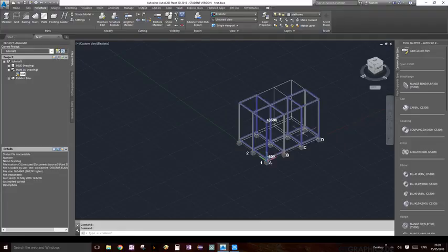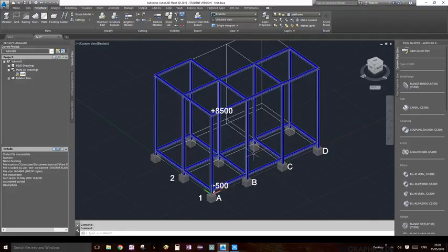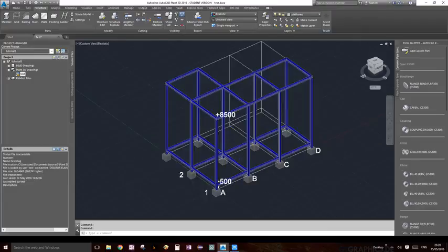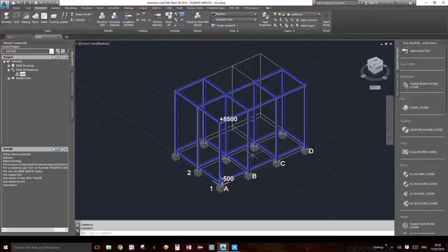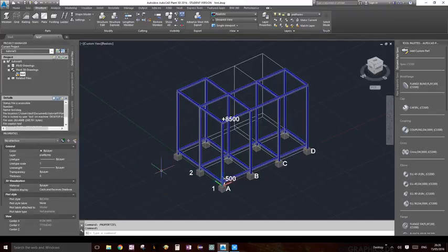Okay, so another thing that we're gonna use on and off quite a bit is the properties window. I find that it's sometimes super easy to just change the numbers than actually physically change the object. So in that case, you can just go into the properties window and quickly change some of the attributes. So to open the properties window, just as long as you're in AutoCAD, start typing properties. And as you can see, my first option is properties. Go ahead and click that, and just like so, your properties window should pop up.